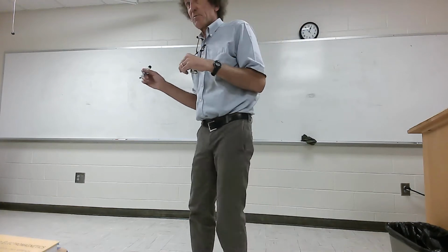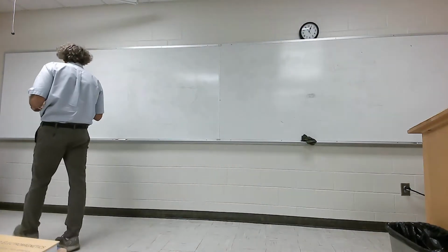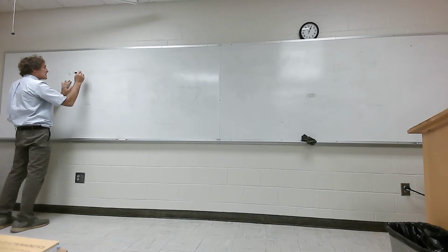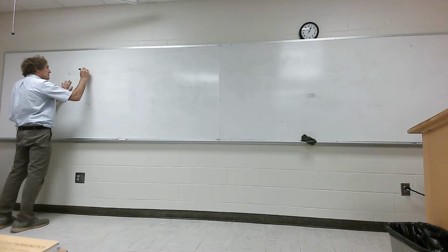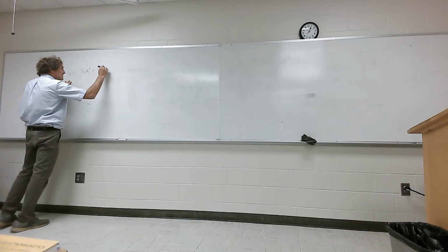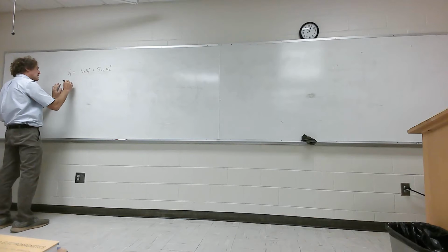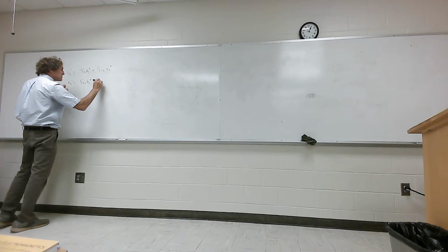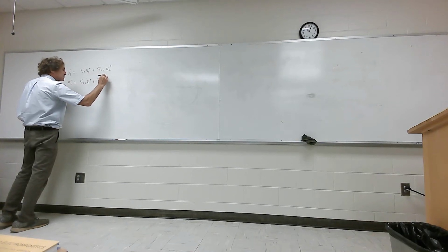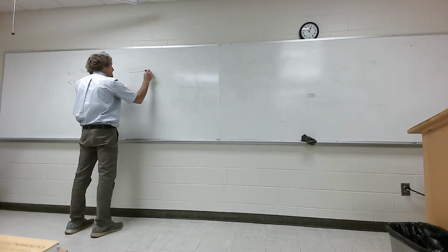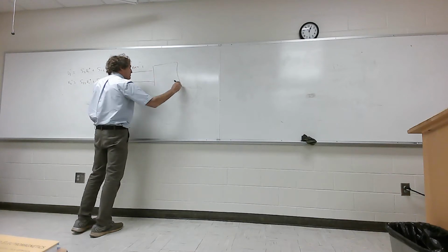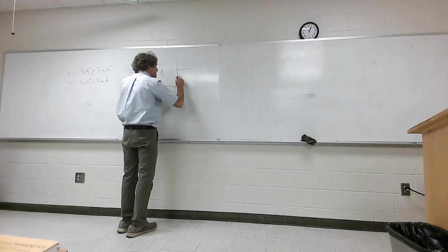Okay. Back to S parameters. I'm just going to review this and go through some examples. So when you have S parameters, generally we talk about V1 minus is equal to S11 times V1 plus plus S12 times V2 plus, and then V2 minus is equal to S21 times V1 plus plus S22 times V2 plus. And this is a simple two-port, so here, this would be port 1, and here would be your S parameters, and this would be port 2.